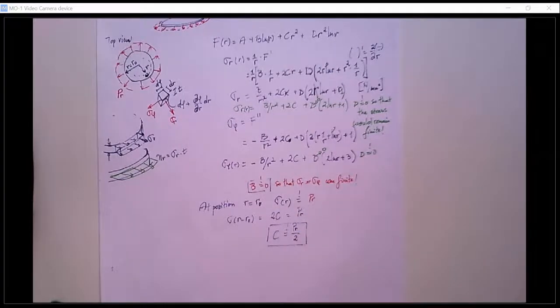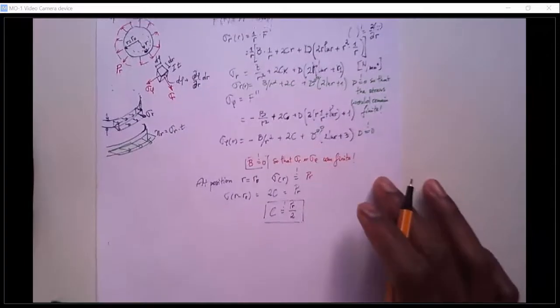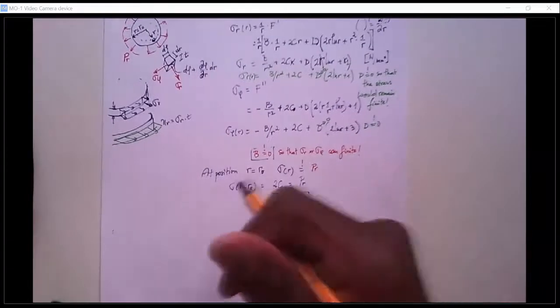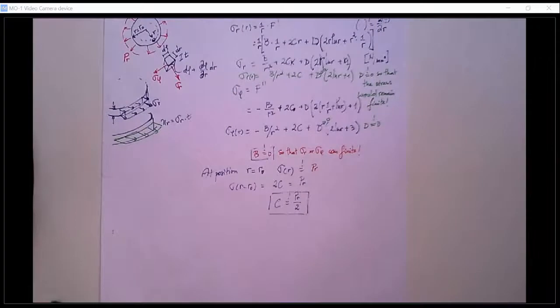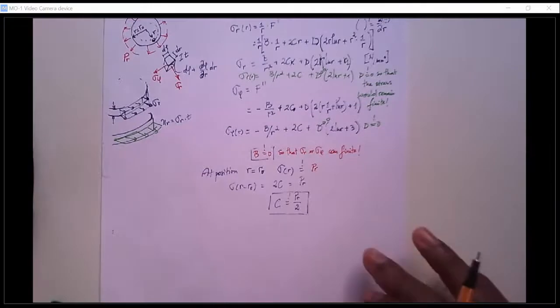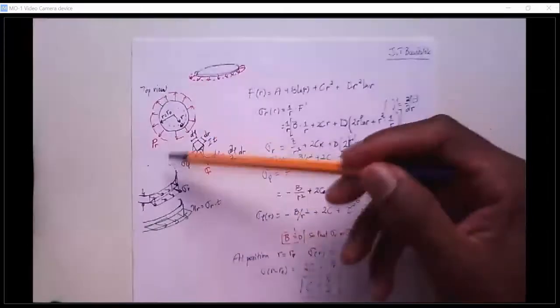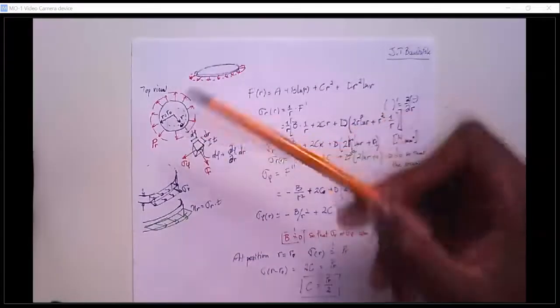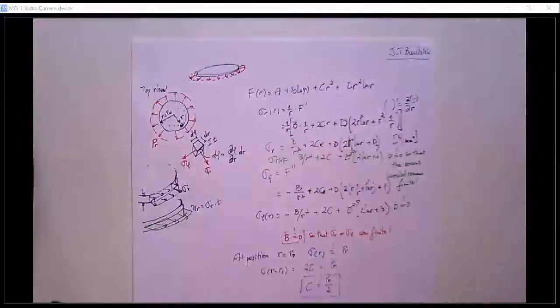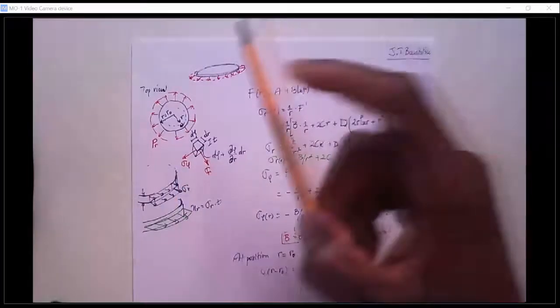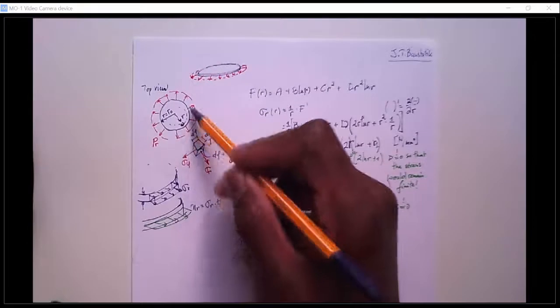Okay, there's something else that's very important to know here. The stresses are positive when we have stretching, basically. So when we have elongation of the element, or when the element is under tension, and they are negative when we have compression. So basically, the stress that we have here is kind of elongating the disk in the radial direction. Those are like tensile stresses in some sense, at the boundary at least.